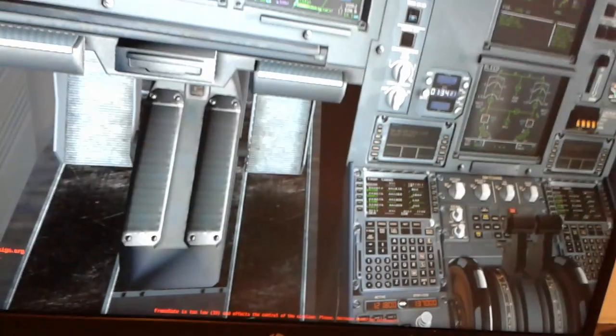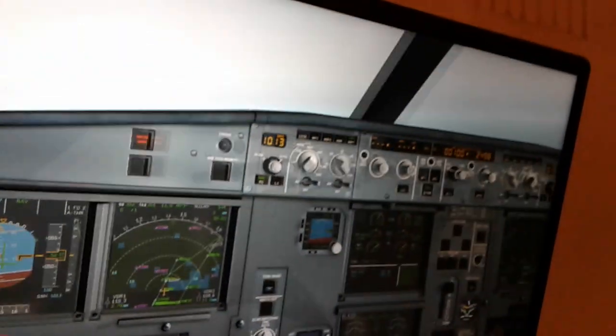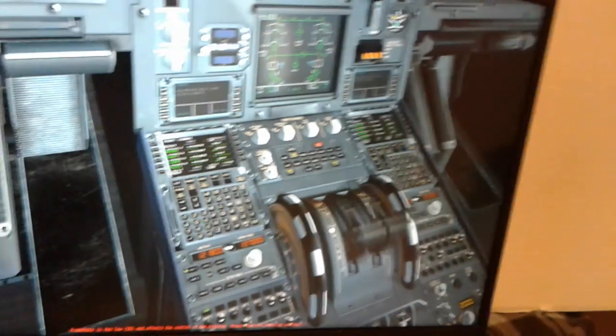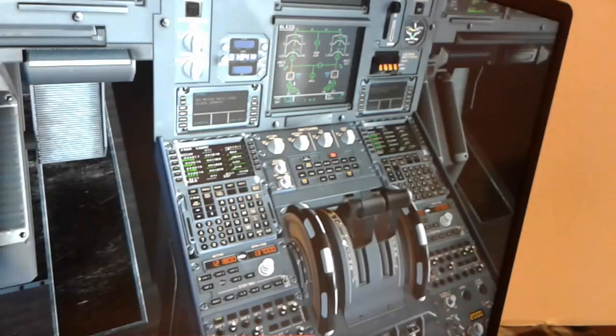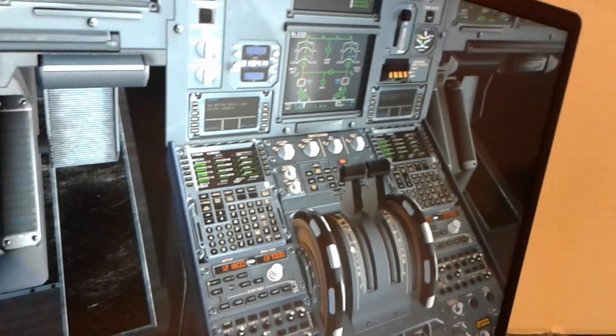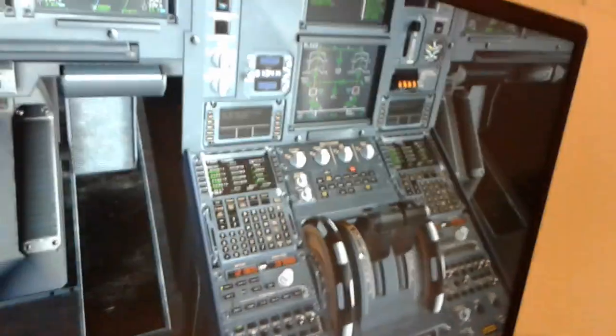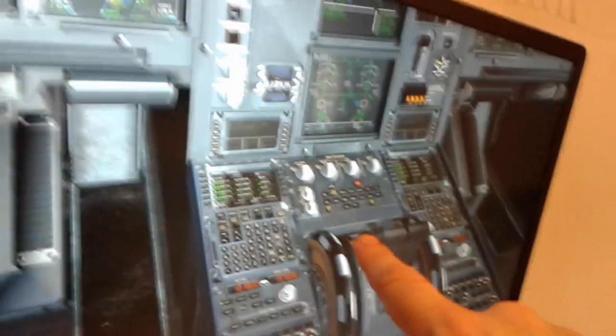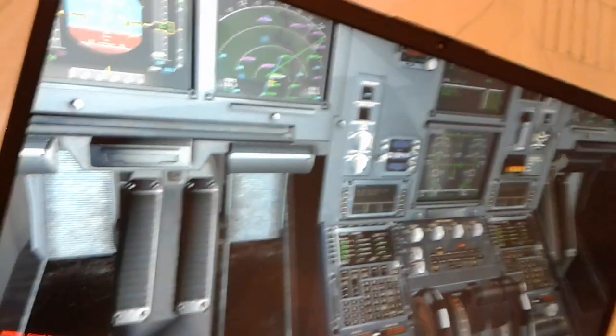So we reach the maximum airspeed. We need to climb. This is actually the climb detent. From idle to climb is the manual thrust. After climb, the thrust setting is automatic from the auto thrust system. So we have the flex and the takeoff, and the climb, and we have the reverse thrust also, for idle and reverse.